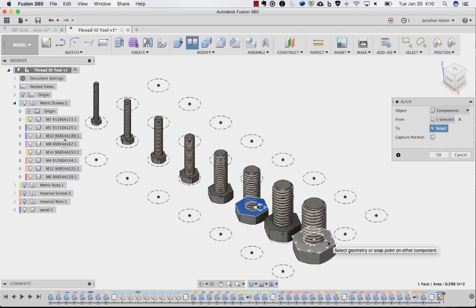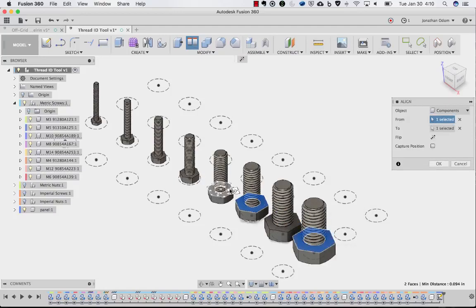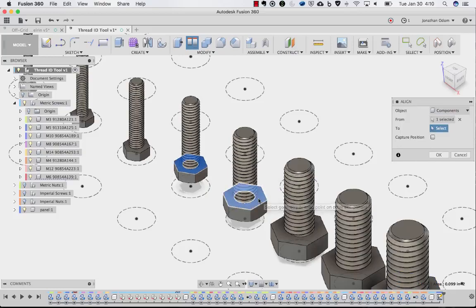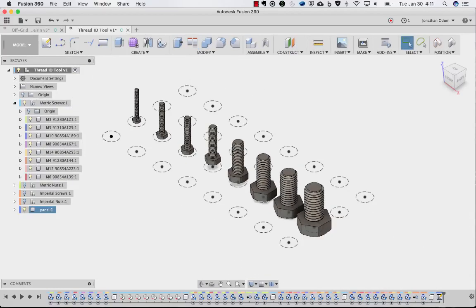So as long as it's anywhere on that top surface from the other one, even if the other one has that little square cursor, it's going to just move up in that direction. You don't want it to move in the X or Y. You just want it to move in the vertical, Z in my case. I'll click OK so I don't lose my work if I make a mistake here.